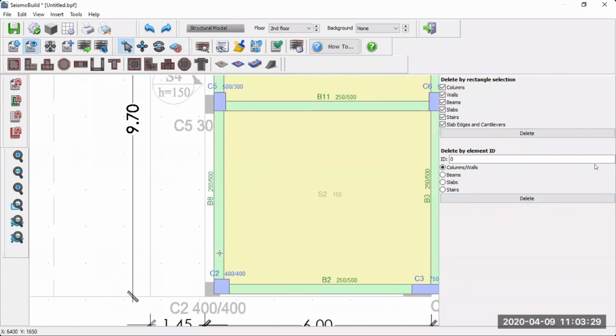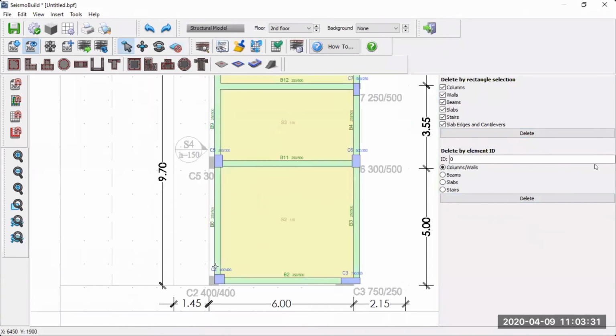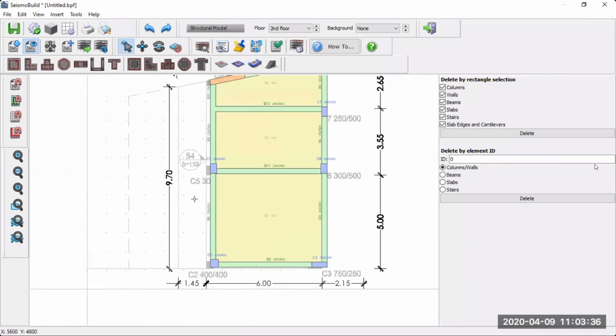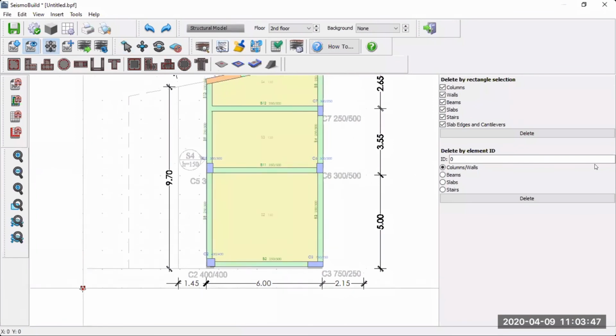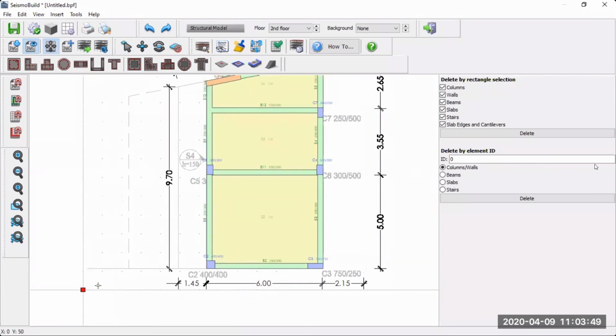And also you notice that the drawings are not in line. So how we're going to do is, we're going to move our drawings. There are two ways you can do that. First thing, you can select this function, move the exit center. Once you select this function, you notice there's a red dot here. You can move the structure to exactly in line to this building. Okay, there's one way you can do that.